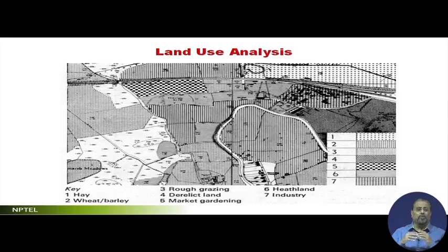In the whole design process, when you are going to take these decisions, for each one of them I have one suggestion, and you take it very seriously. If you are analyzing with respect to land use, then you must shut off all your analyses for the rest. At this point you are focusing only on the land use analysis. You are not checking the slope, the contour, the hydrology, or anything else. You are checking only land use. Focus on this analysis, and whatever transpires from it, write it down as an inference.